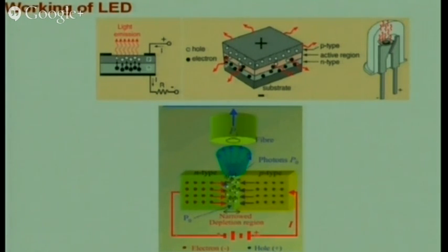Now you can see this light output is coming out in all directions, right? What I want is this light output to be coupled to my outside media. My fiber is at one point, right? It cannot be at all the points. So I must confine this active region to a narrow region, so that I can couple maximum output to the outside media or fiber, right?